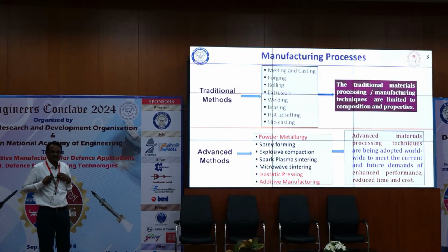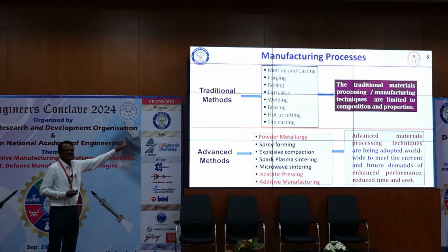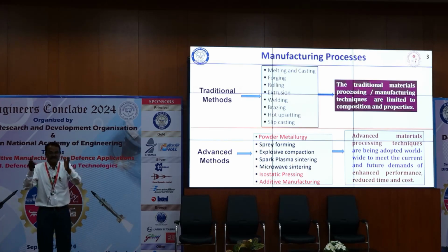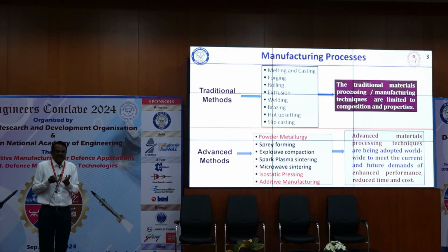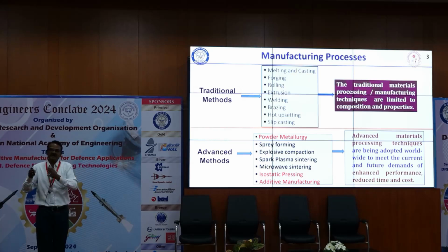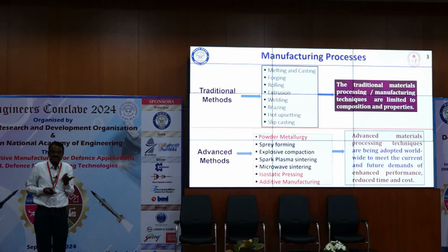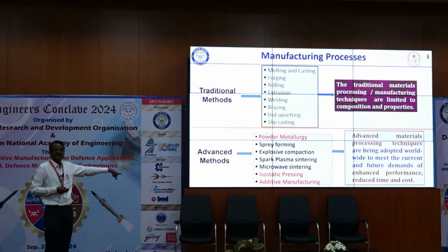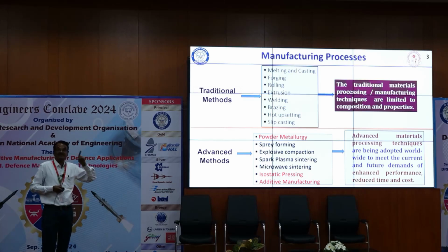Now, processes. I am a processing person, spent so many years at DMR, traditional melting, casting, hot extrusion, forging and all the traditional things, but the traditional processing technologies have a limitation, confined to certain compositions. Including 718, low volume production, easily processed. You can do forging, rolling, extrusion, everything. But recently DMR has developed 5 new alloy compositions. Can anybody handle it? Can anybody process it? Very, very difficult. So therefore, advanced technologies, powder metal, many things are there. But in today's context, I would like to emphasize isostatic testing and additive manufacturing. They are very important.